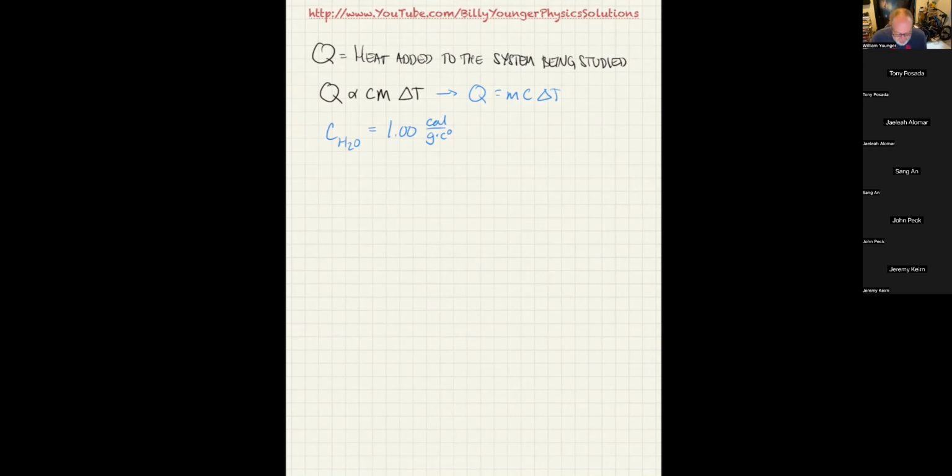Okay. So in reality, if you were doing a big engineering type project where it's very important to get exactly the right result, then you need to check the specific heat that's closest to the range of temperatures you're dealing with. Even though water is supposed to have 1, that's water at 1 for a specific temperature range, which again, I can't remember off the top of my head, but for some reason I was thinking it was like from 13.5 to 14.5 or from 14.5 to 15.5. I might be completely wrong, but that's what I seem to recall.